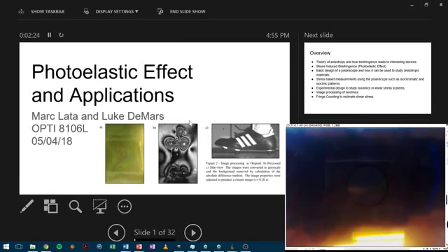So what they did was have a runner at full tilt speed step on a plastic material, and as a result of the runner stepping on the plastic, they would induce birefringence in the material, and they were able to measure the stress pattern of that gait, and they were able to study how different types of gaits can affect impact. Anyways, moving on.